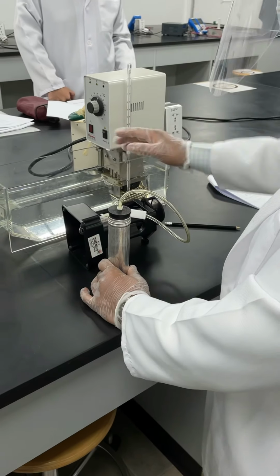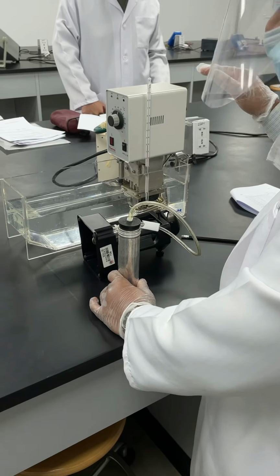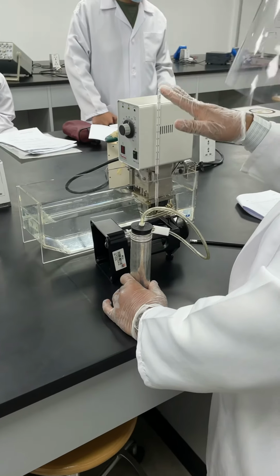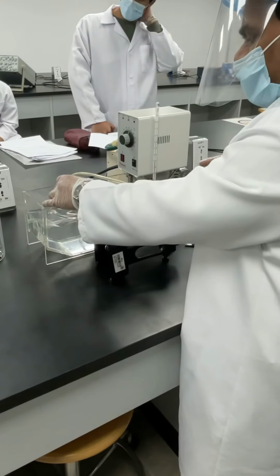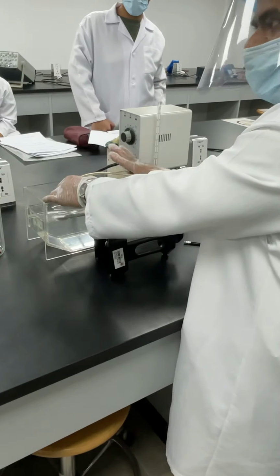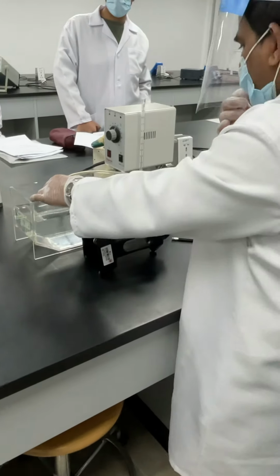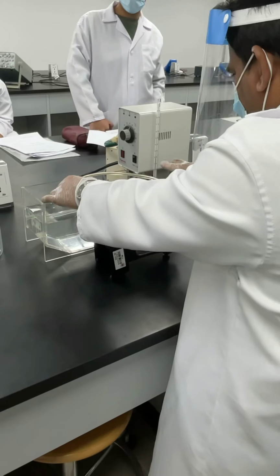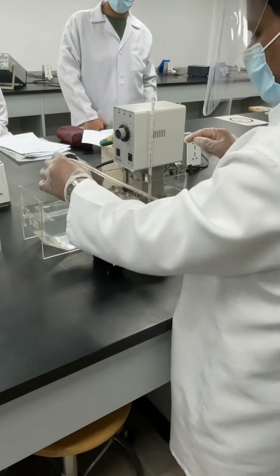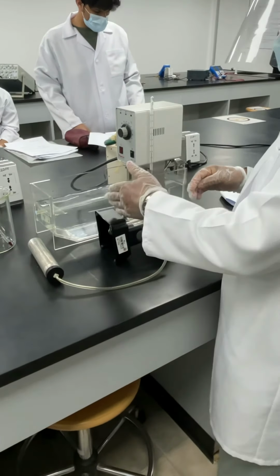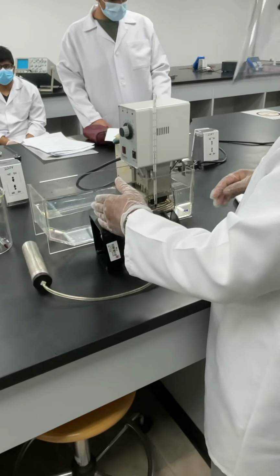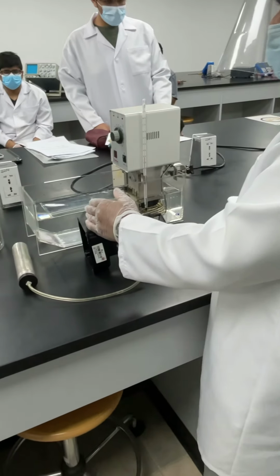Switch on this, it is heating. 30 degrees, 1 degree less than that, 29. When you see 29 here, put this inside the water. Except the rubber part, the rest should be inside the water. Now continuously look at this. When it touches 30 exactly, see how much distance the piston pushed up. The bottom of the piston, you have to say this in millimeter. That is your L. Clear?